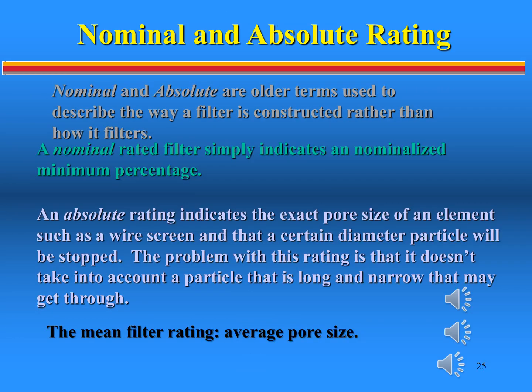The nominal rating refers to a filter capable of cutting off a nominated minimum percentage by weight of solid particles of a specific contaminant. Usually glass beads are measured to determine this. The specific contaminant is greater than a stated micron size, normally expressed in micrometers, for example 90% of 10 micron.